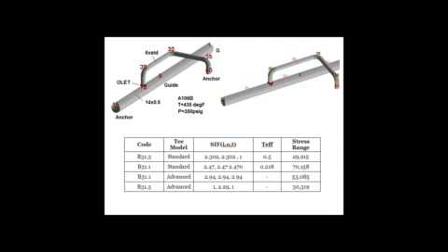With this next configuration, if we look at the stresses, you can see the stress ranges. This one was to point out the differences between B31.3 and B31.1 and using the FEA tools models and not using the FEA tools models. So what you see is that B31.3 gives us a stress range of 29 KSI. And B31.1 gives us a stress range of 70 KSI. Now, what causes the difference? Well, when you look at the system and remember what we said before, you can see that as that branch thermally expands, it's going to put torsion about that OLET. And we know that B31.3 does not intensify the torsion.